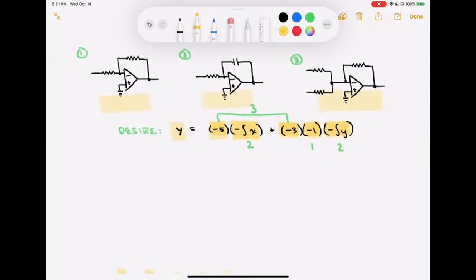So let's go ahead and work our way on that. The way I'm going to start is I'm going to think about what it is that I'm trying to do. I'm looking first as I work my way left to right across there. I see that I'm going to need an integral x. And so I'm going to go ahead and do a little cleanup up here. I'm going to make it so that I can grab each one of these, and I'm going to grab one of these integrator circuits.